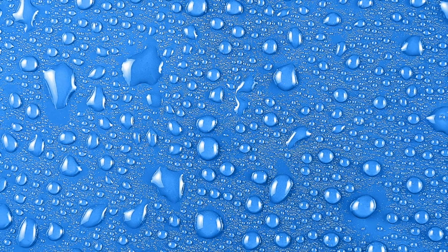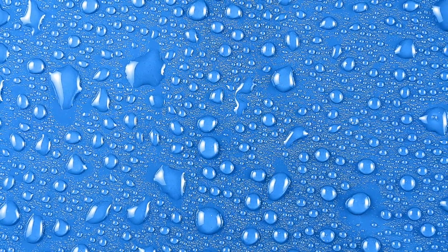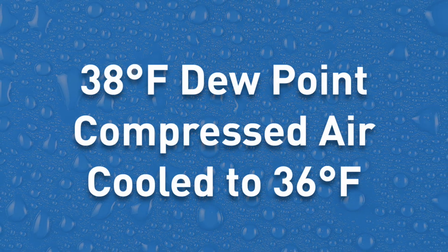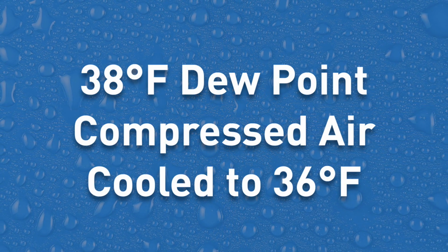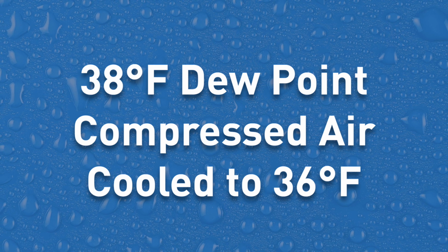Pressure dew point is the temperature at which the air in a compressed air system is 100% saturated with water vapor. When compressed air is exposed to a temperature below its dew point, the water vapor condenses into liquid water within the pressurized distribution system.